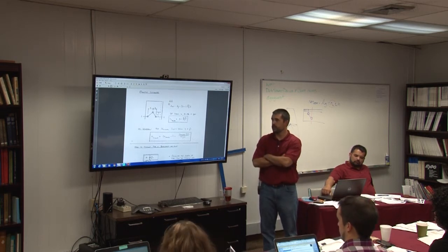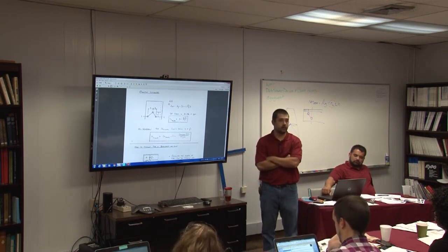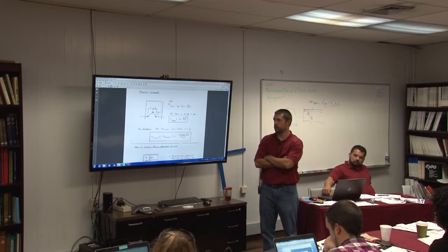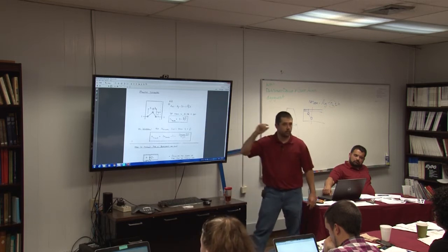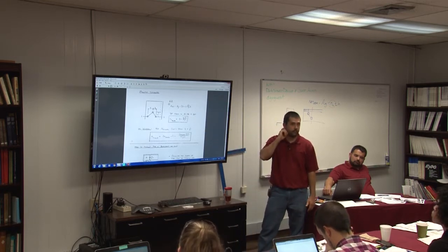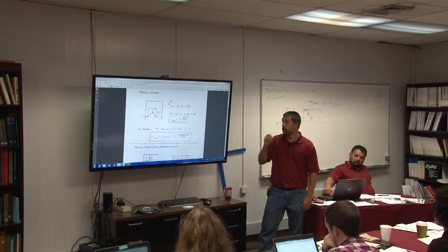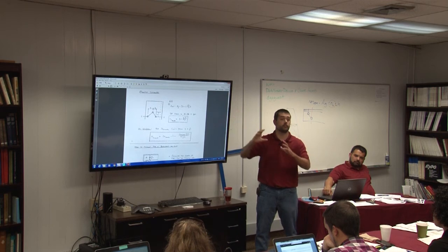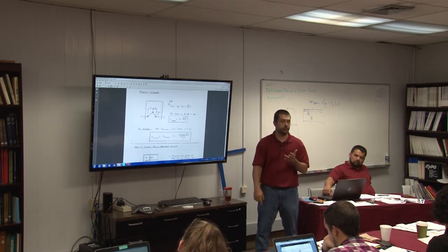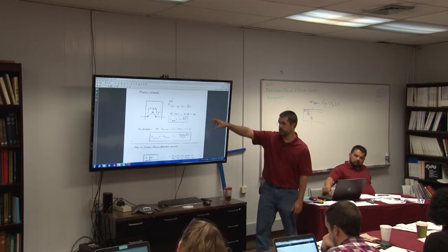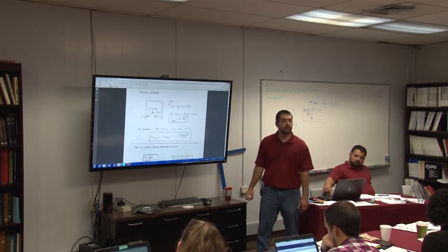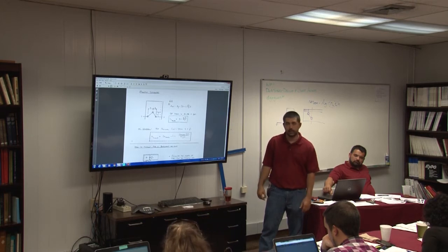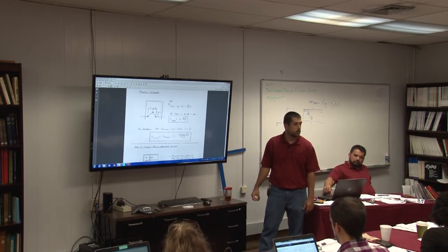No, and I think a lot of it is because there's already a lot of variables. Connection modeling is already difficult, and if you really get into trying to specifically lay out exactly where the holes are, it's really going to up modeling time tremendously. Whereas with stuff like this, you've got the equations. It's pretty easy to build a very simple spreadsheet. What's the hole size? What are your gauges and your spacings? And you can figure that stuff out pretty quickly. And that's what we do. We have stuff that you just input, and it tells you the equivalent number to put in.